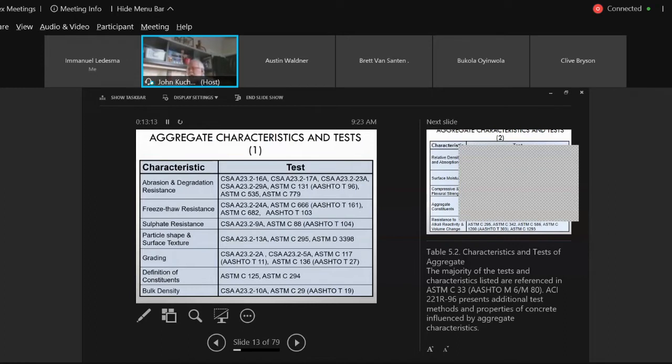Our Winnipeg soils here locally and in the Red River Valley are very, very high in sulfate concentrations. And soluble sulfate in soil can attack normal Portland concrete. Our normal Portland concrete that we're going to use in the pavements is classified as GU, general use. A few years back, it was type 10. The states still use type 1, type 2, type 3. We go to different designations, and when we're talking about cement, you'll see the 6 designations. But sulfates can attack normal Portland GU cement and deteriorate it.